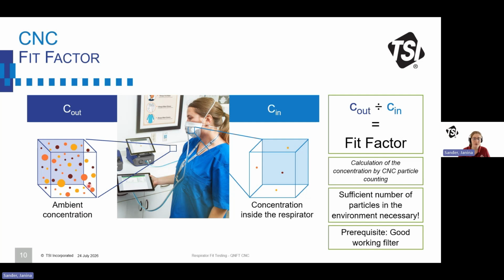If you imagine you have a very low number of particles here in this box, you can't find a higher number inside the respirator, even if the mask is not fitting. So you need a sufficient number of ambient particles so that you can really say, if I don't find particles inside the mask, then this is due to a good fit and not just because there couldn't be more particles coming in as there weren't more outside.